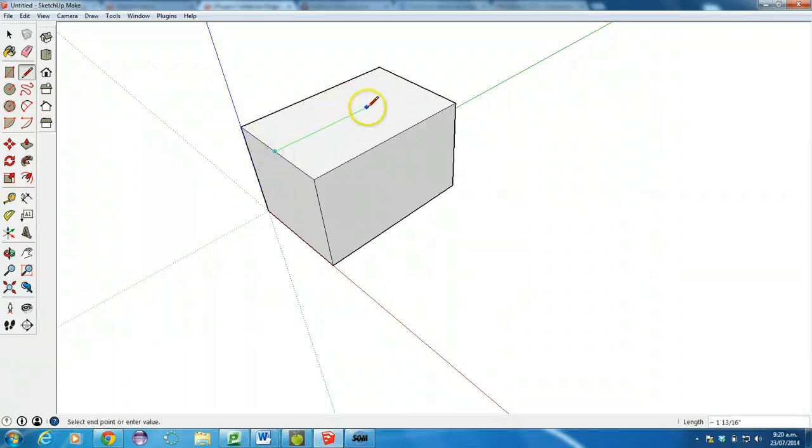What I want to do though is use a midpoint here, click and drag across here. Now you can't work visually in 3D. What I mean by that is you can't just guess that, well, that looks like a straight line across there, because it's not. Google SketchUp will show you when it's a straight line by giving you a color that tells you this is exactly on the green axis, or in this case, there are ways to make it parallel to another object. But say I did this here and just drew that there.